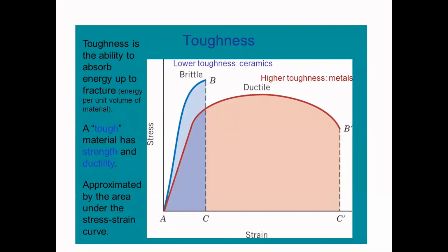Its value is equal to the entire area under the stress strain curve, like what we can see in the figure here. In most cases, the area under the elastic portion of the curve is a very small percentage of the total area, and we may ignore it in the calculation of the modulus of toughness.